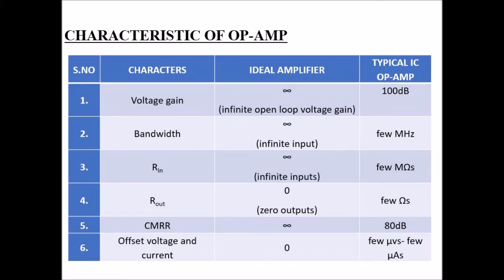And one more thing, for each and every measuring technique, the bandwidth cannot be altered. That should be predetermined and pre-requested. If the device is connected for ECG, then the frequency is already preset and it will operate by switching to that bandwidth. And input resistance.